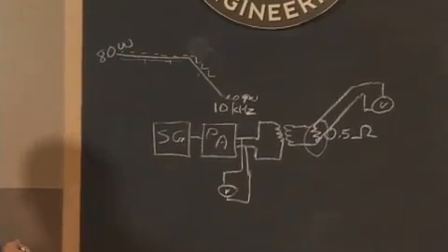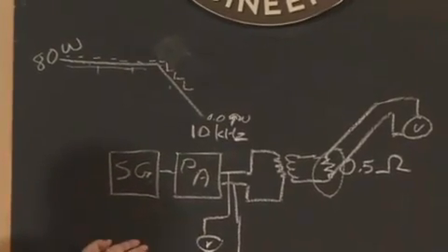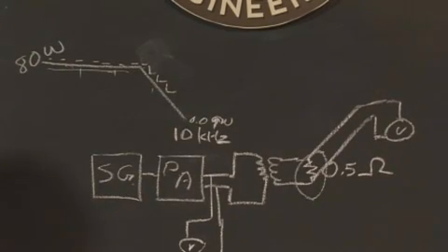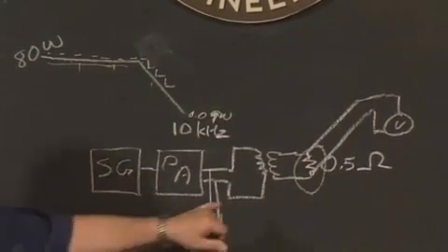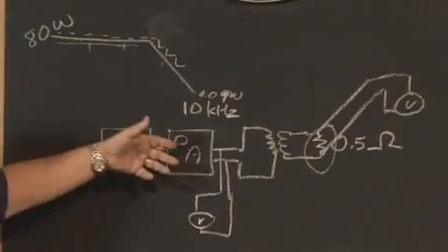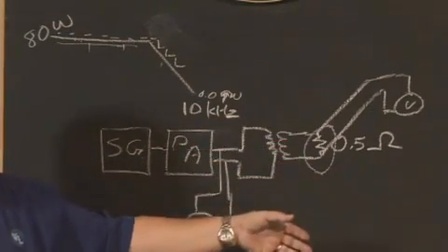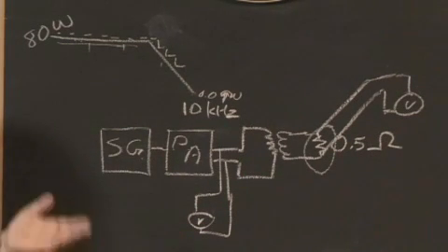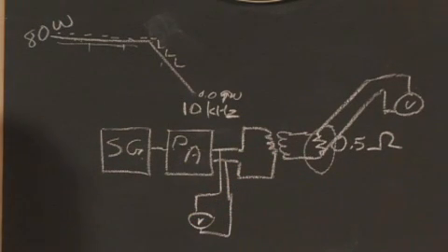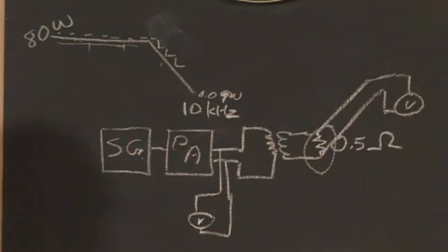And that process goes on until we have all the frequency ranges needed to determine our calibration. This establishes a maximum power. Why do we need that? If the test article happened to be a very low impedance, as in lower than 0.5 ohms, we would try to put more power into this to try to create a voltage across that resistor or the load circuit of the test article. However, we don't get there. We keep increasing the drive power until we develop that or we burn something up in the process. So the goal is the lesser of this pre-calibrated forward power or the test voltage.